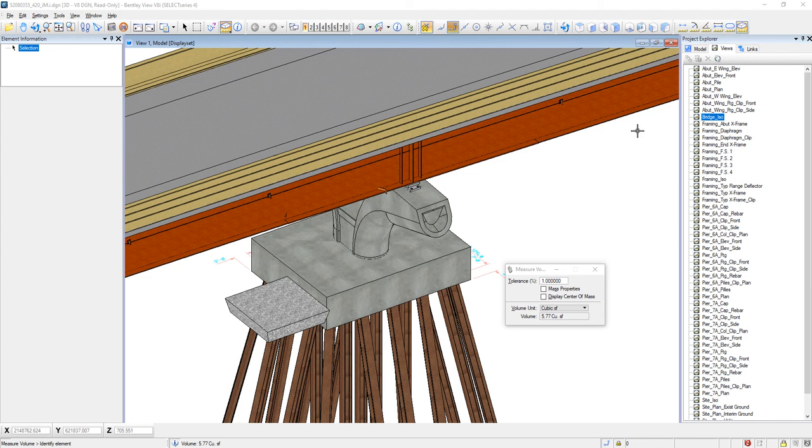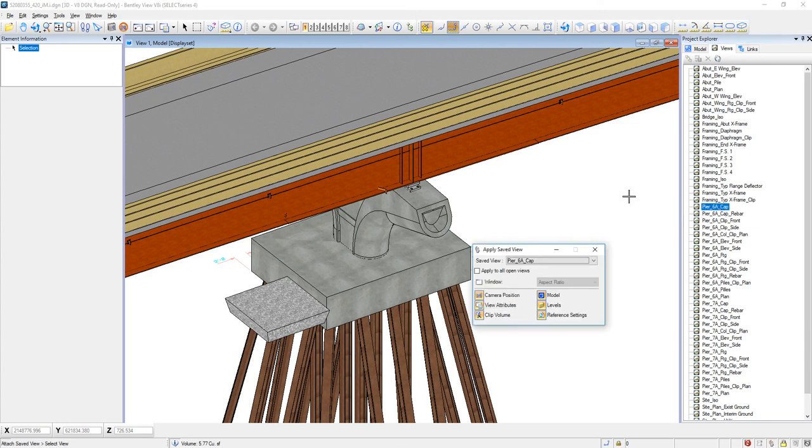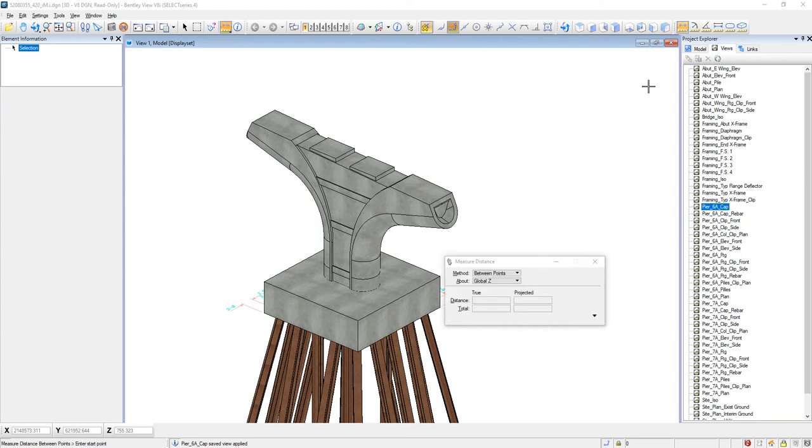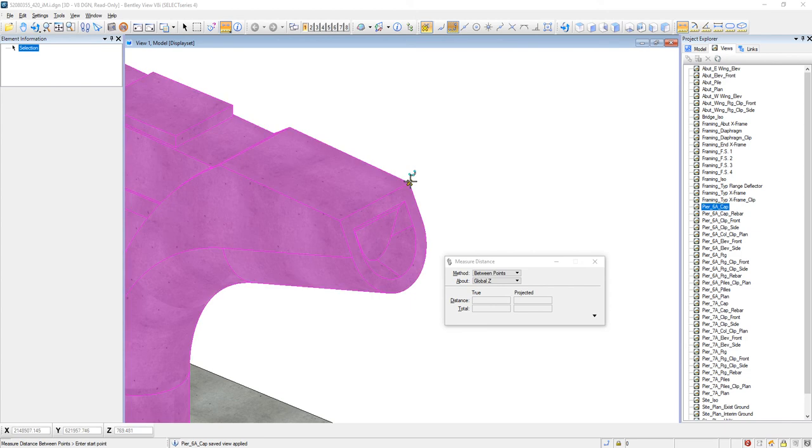So if I wanted to measure an elevation, for example, let's go back to our pier. What I typically like to do is select a tool that allows me to snap to certain elements. And again, we'll talk about a little more detail on these snaps soon, but snaps are basically these little yellow X's that identify key points or breakpoints in the element.